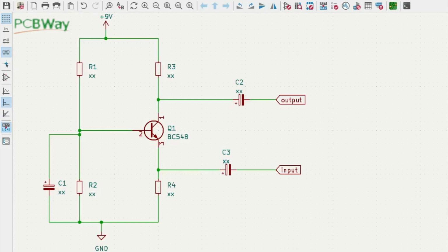This is the common base amplifier configuration where the base is said to be common to both the input and the output. This circuit gives less than unity current gain but can provide quite high voltage gains. So just to give a quick idea why the current gain is below unity, e.g. less than 1, let's have a quick look at the circuit.